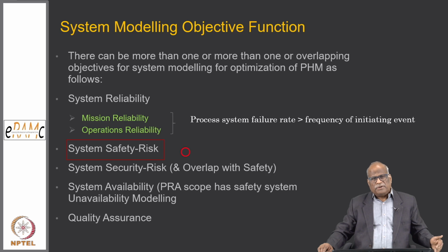What was the availability factor during the year for a plant, and if I plot say 10, 20, 30 years, I will know. And these charts are very important because you want to know what is the status of the plant, whether it is operating at full capacity or at 80% capacity or at 50% capacity. If it is operating at 50% capacity, how the capacity factor has dropped, and probably it might be an indication of the plant aging after 20, 30 years or so. So system availability also provides a very good metric.